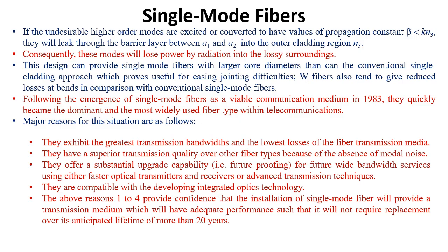Following the emergence of single mode fibers as a viable communication medium in the early 80s, they quickly became the dominant and most widely used fiber type within telecommunication systems. The major reason for this, that is why we are going for single mode operation, is that they exhibit the greatest transmission bandwidth and the lowest losses in the fiber transmission media. They have a superior transmission quality over other fiber types because of the absence of modal noise.